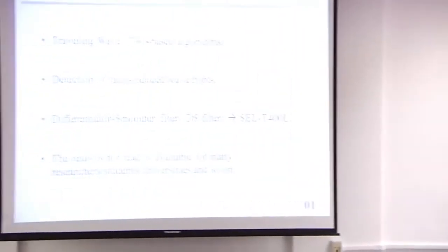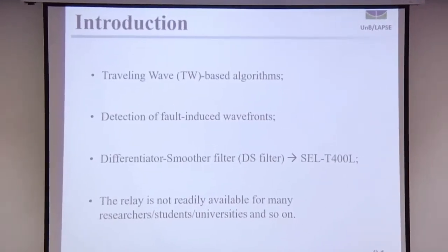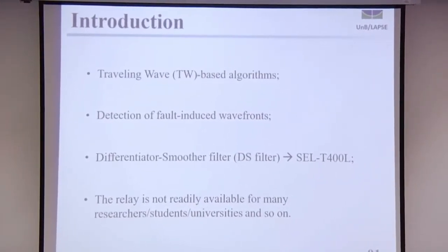There are many filtering technologies used in TW-based applications, where the differentiator smoother filter, called in this paper the DS filter, is used in an actual time domain relay, the SEL-T400L, where the DS filter original routines are embedded for protection and fault location solutions. Due to that, the DS filter has shown to be promising compared to others.